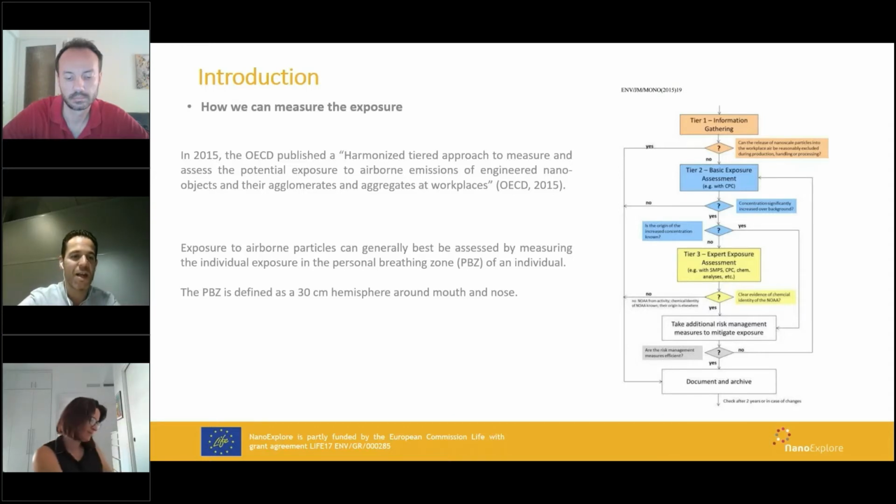At the end, we always have to start with a questionnaire, as you can see in the figure, just to know the potential hotspots or critical areas of release. If we observe that there is a potential for release, we can measure number concentration with simple instruments, for example particle counters.